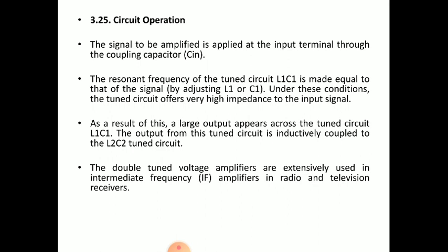The output from this tuned circuit is inductively coupled to the L2 C2 tuned circuit. The double tuned voltage amplifiers are extensively used in intermediate frequency IF amplifiers in radio and television receivers.